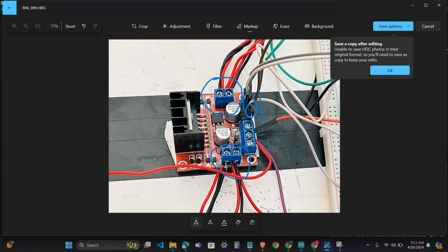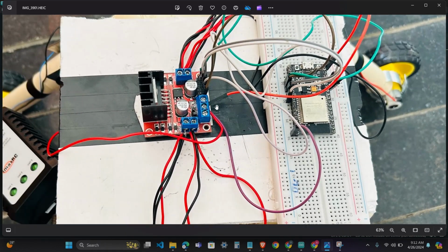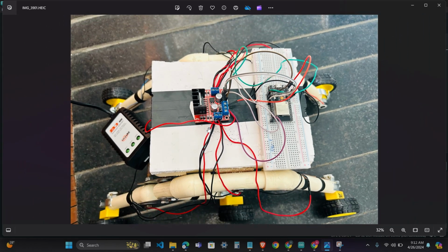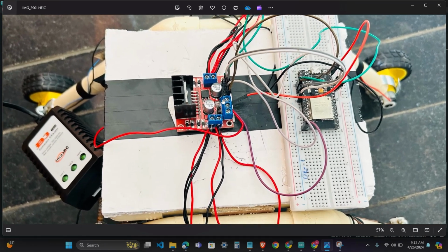Two digital inputs control the inputs to output 1 and output 2, and the other two digital pins control the inputs for output 3 and output 4. The analog pins decide the amount of voltage which reaches the motors. If you want to control the speed, it can be given through these two analog pins, which reduce the amount of voltage which reaches the motors. So in total we need six inputs to control our rover, and we used only a single motor driver to control all six motors.